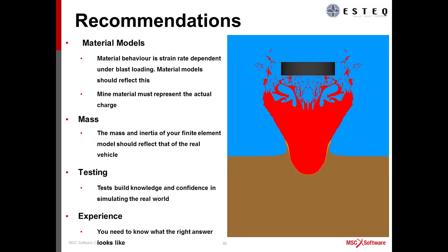And then the final 2 points on this list of recommendations go hand in hand, and that is testing and experience. As I've mentioned earlier, you will not escape testing in this scenario. It's necessary to build knowledge and confidence in the simulation models that you build. And also, experience of mine blast tests allows you to have a better idea of what the right answer will look like. I know that doesn't sound good, but that is the truth. You need to have some sort of knowledge of what to expect given a certain charge size and vehicle hull shape and plate thicknesses and that sort of thing to verify that simulation models are providing useful results.